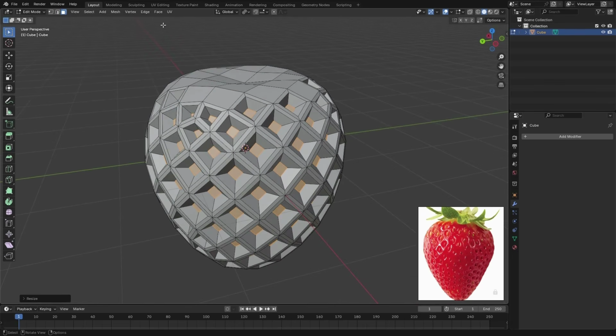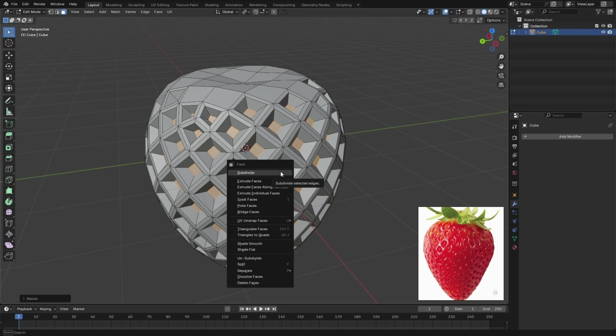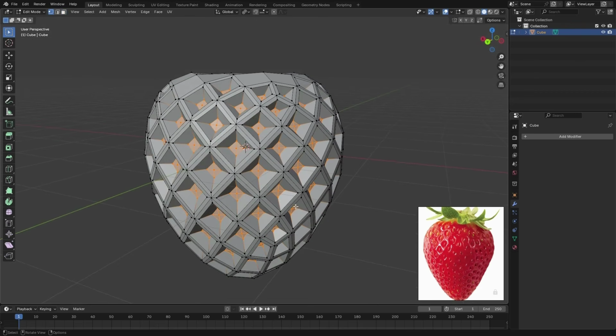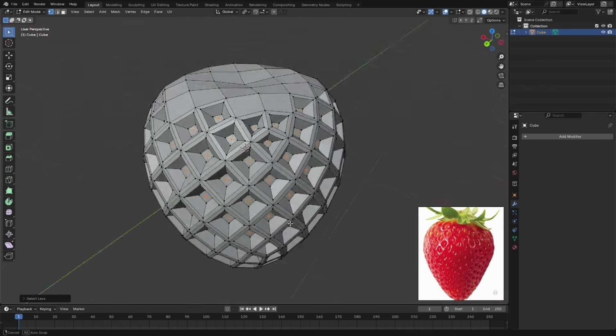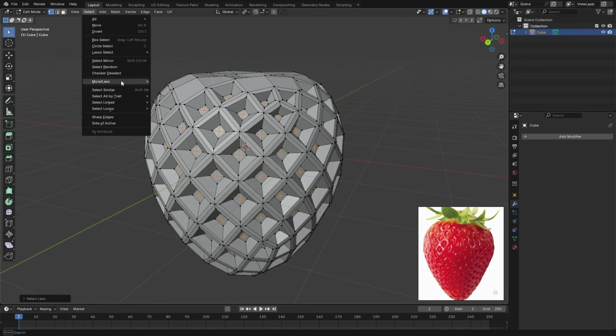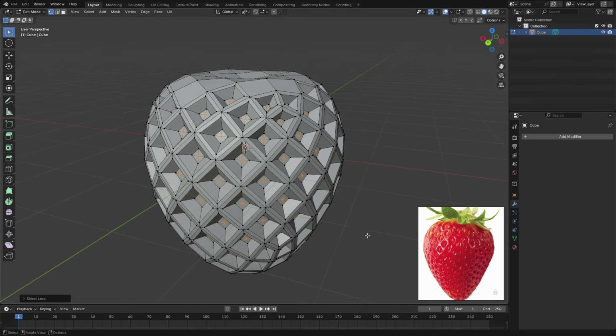So let's go ahead to the face and right click will do. So right click and hit poke face. Switch back to the vertex and hit Control minus on your numpad. Or if you don't have a numpad key, simply go to selection and here more or less, numpad plus, numpad minus. All right, let's go and store these vertices.